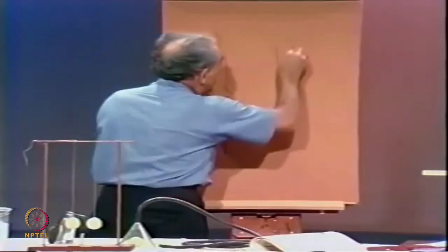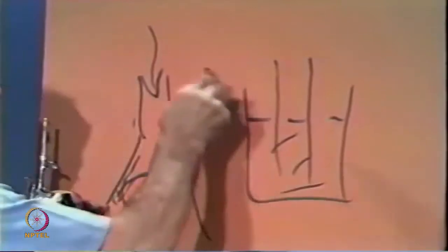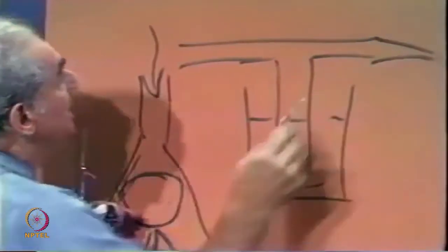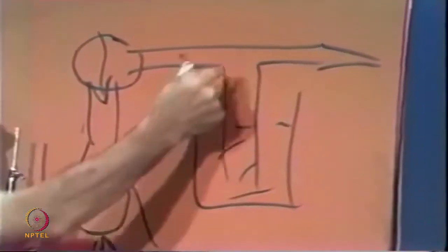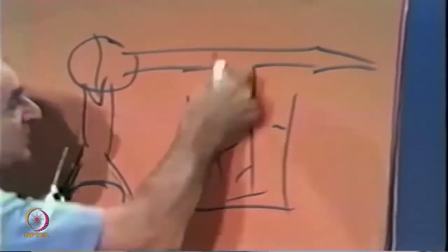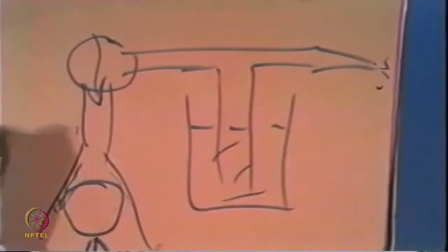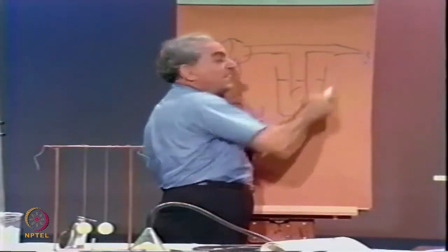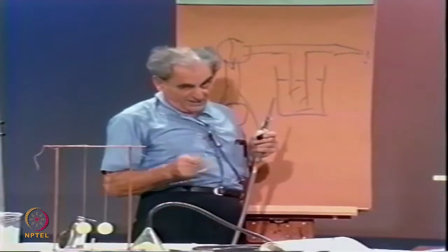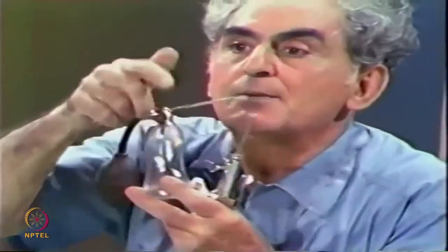An atomizer is a tube that resides in a vessel, and here is some liquid, and here is a tube across here, and here is a bulb. You squeeze the bulb, air rushes across, there is a reduction in pressure, the atmosphere pushes the liquid up, and then the liquid is caught in the airstream and comes out there. I have often thought that the reason that's called an atomizer is because little atoms of the liquid come out there. Don't you like that idea, little atoms? Now, here is an atomizer, and spray would come out there.